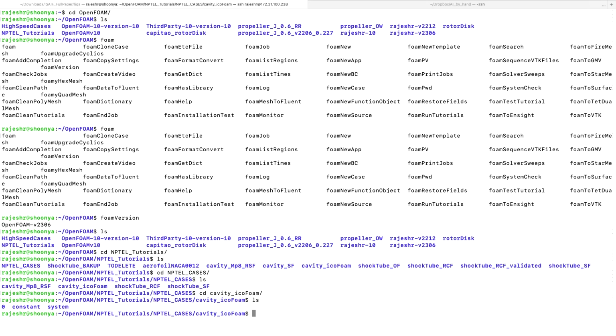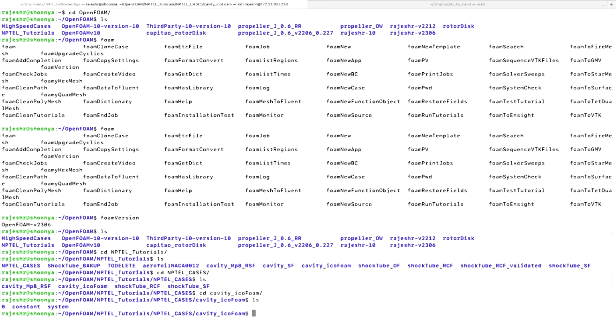There are many solvers present in OpenFOAM. Those who have not used OpenFOAM till now, please go back and take a look. You already have many solvers and many tutorials given there. In fact, you can edit those solvers to solve your own problem. You just need to find out the appropriate solver that you need. There are solvers made for transient problems, where the flow is varying with time, unsteady problems, and there are solvers made for stationary problems, which are steady state problems.